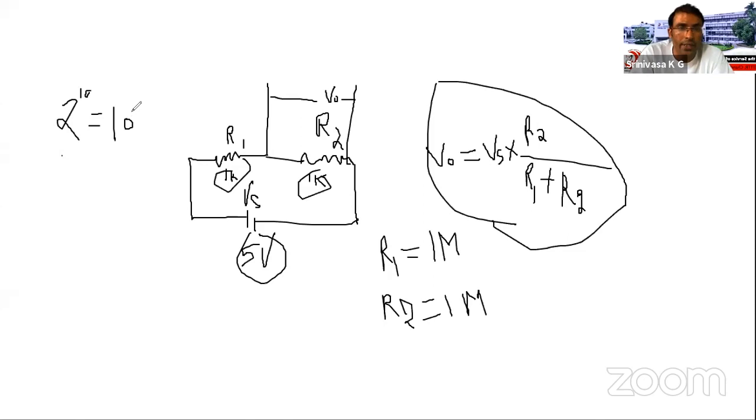1024 is the total number of values, but in bit or byte, whenever we read, we consider 0 also. So we are reading 0 to 1023. If we supply 0 volt to Arduino, then Arduino will read 0. If we supply 5 volt, then going from 0 to 5 in increasing order, our value will increase in this order, 0 to 1023.